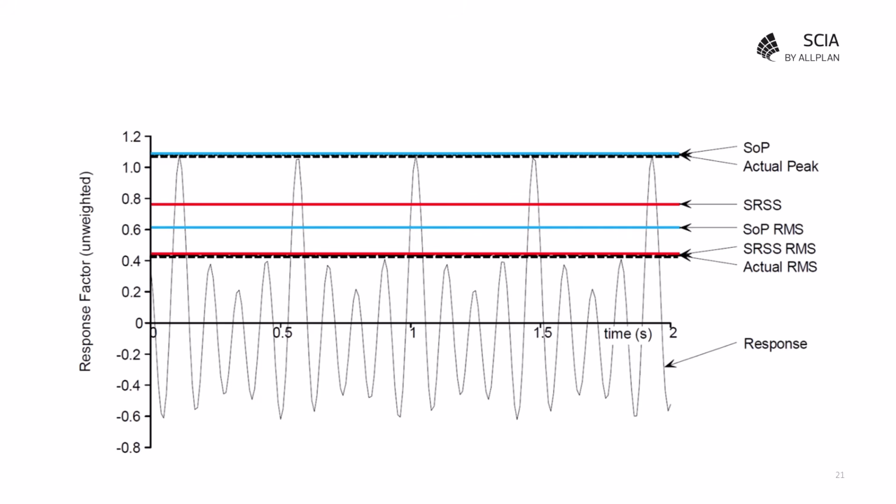Less conservative methods, like SRSS, consider the steps as uncorrelated events, leading to lower and more realistic estimates that might better reflect random footstep timing. Just remember, choosing the appropriate method is essential to comply with the selected design method. So you should always refer back to the design method that you're using.